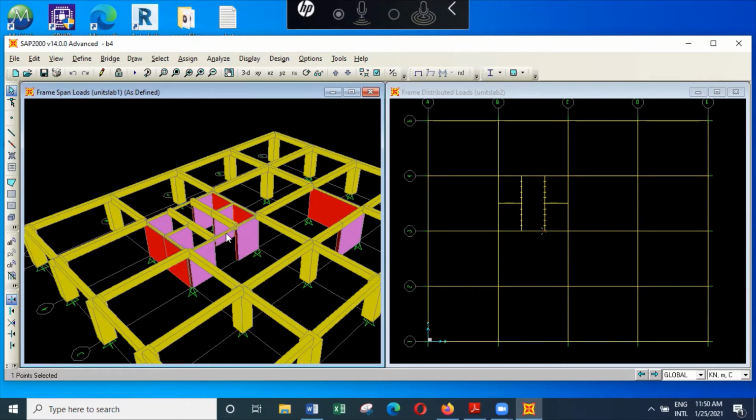Whereas, if you want, you can provide a bigger beam than this because the floor to floor height is 3.6 meters. And the lift lobby entrance area can have a height of about 2.4 meters. The reason is the size of the lift door will be only about 2.1 meters of height, because you don't need anything more than that for the height of the lift door.